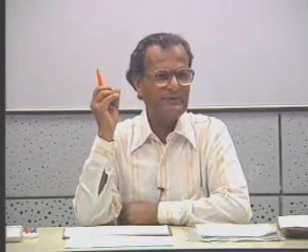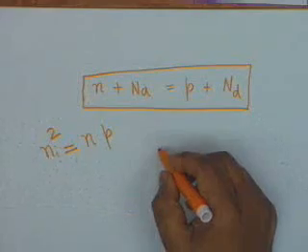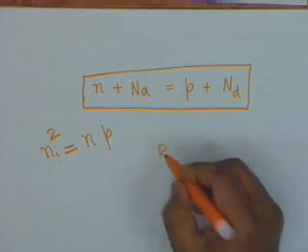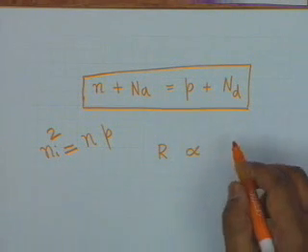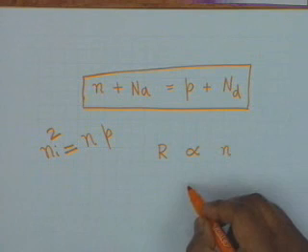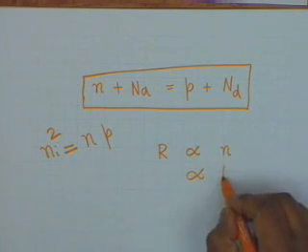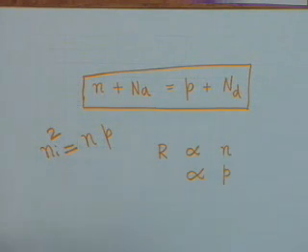Generation is because of thermal energy. Thermal energy is the cause for generation of electrons and holes, and recombination occurs because there is a finite probability that an electron shall collide with a hole, and therefore they will recombine and disappear. Now, normally the recombination rate is proportional to the concentration of electrons. It is also proportional to the concentration of holes.